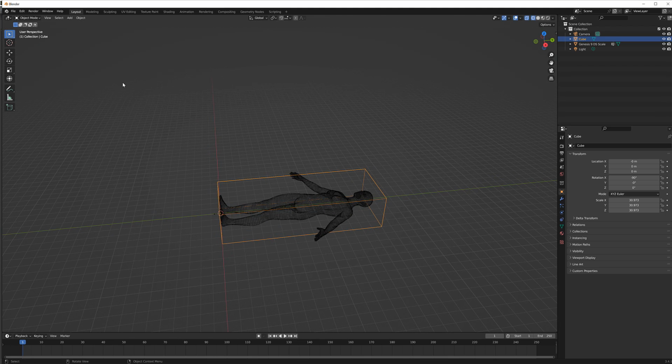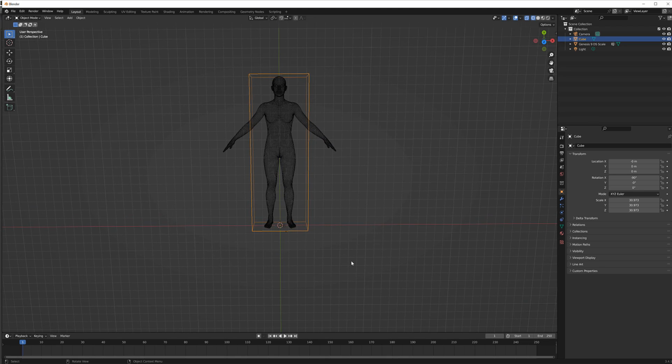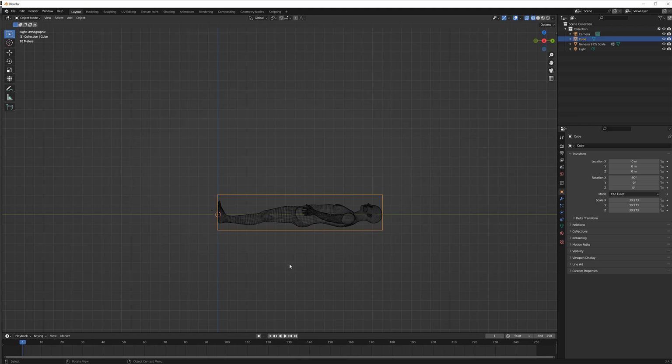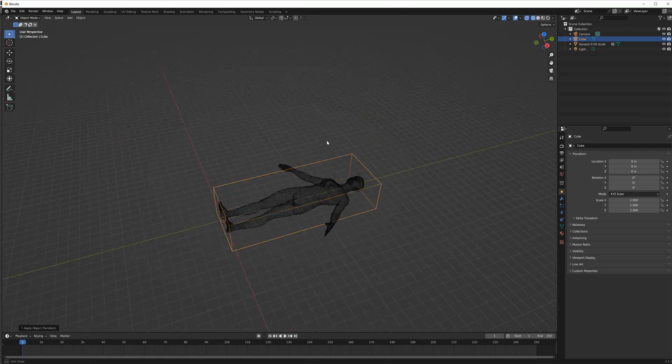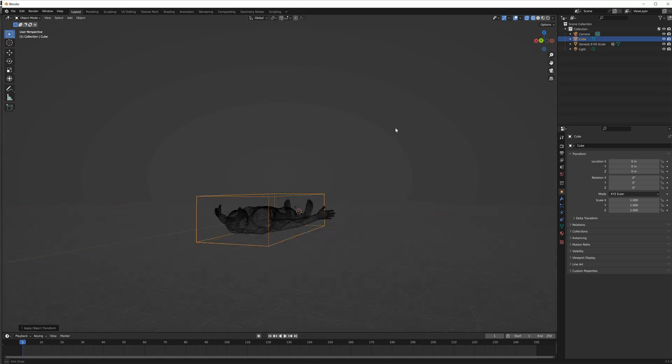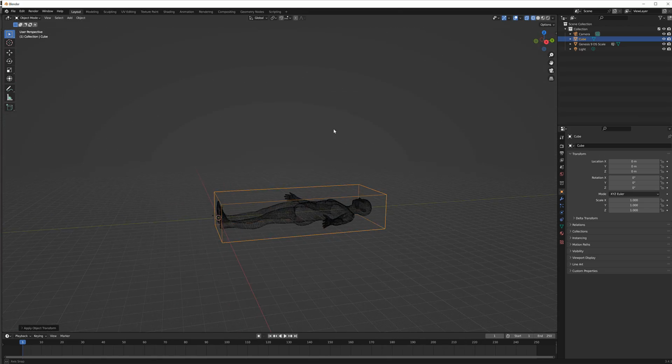Then I'm going to take this and I'm going to make this into a smoke object, because this is what I'm going to use to figure out the difference in smoke object position and scaling in Blender versus Daz Studio. So here is how I'll do that. I've selected this altered cube. I'm going to hit Control A and then All Transforms, which makes sure that our sim isn't messed up by the changes in scaling and position that I've made.